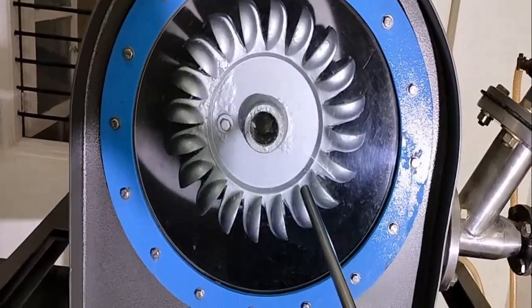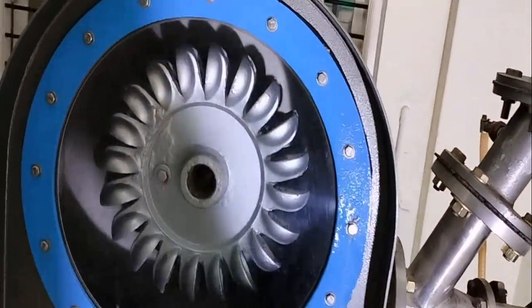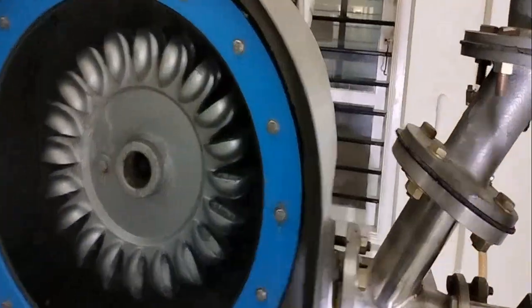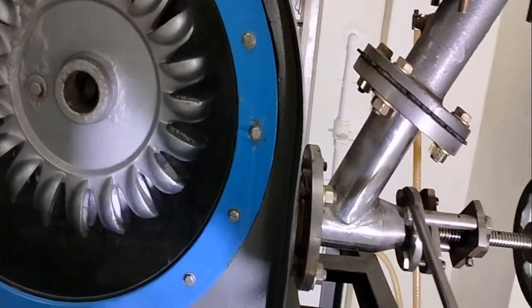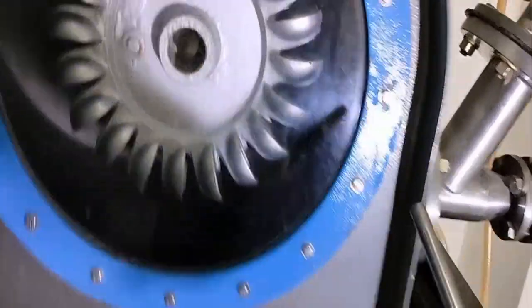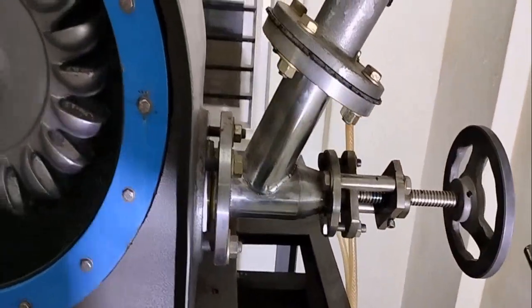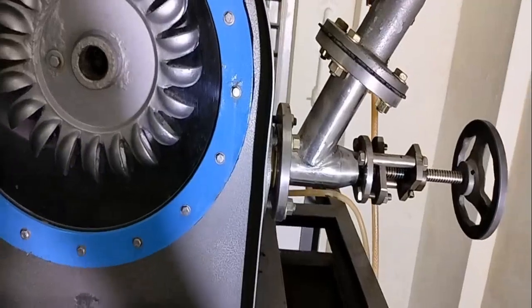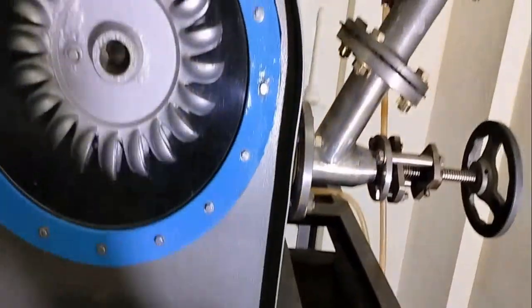So this one is the runner, and the runner is connected to the shaft, where the shaft is further connected to the generator to produce electricity. But here the shaft is connected to the brake drum to apply the load over the shaft at different speeds. And also, to control the water, this mechanism is there. We are going to call this the wheel and spear mechanism. There is a conical-shaped rod. By moving this wheel we can control the water over the turbine. For different speeds we can control the flow of water through this mechanism.